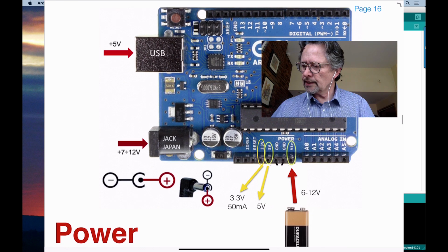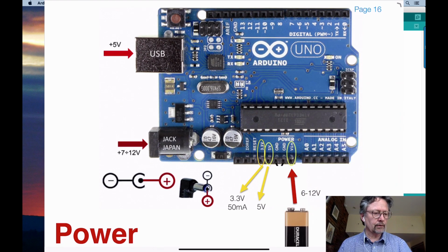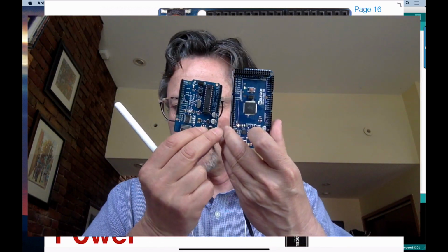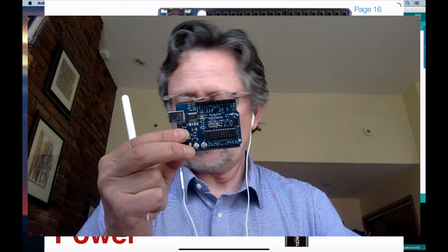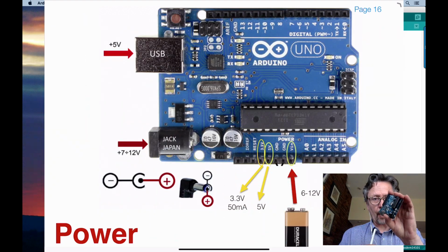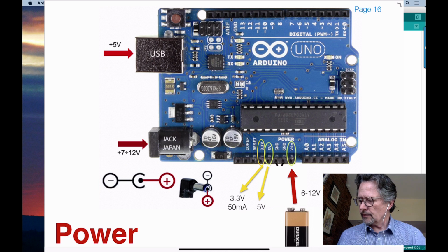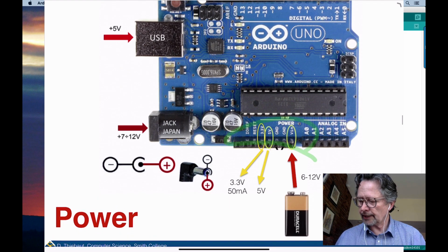All right, so that's the original Arduino, which is slightly different. That's the one we're using. The diagram that we have here shows where the different power pins are, and they're very similar. These two boards that I showed you are similar, pin to pin in some ways, compatible. So the VIN, 3 volts, we see where everything here is. And if we have a battery, we can connect it there.